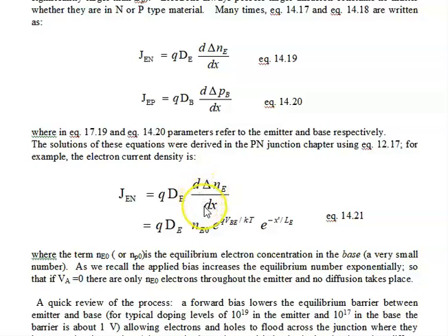Okay, so we know that this whole business here is just equal to the equilibrium value multiplied by the boost, and we're going to assume that it is an exponential decay. It could be, exponentials are more general. It can collapse to the linear if we have a short base, but if it's not a short base, then we use the exponential form.